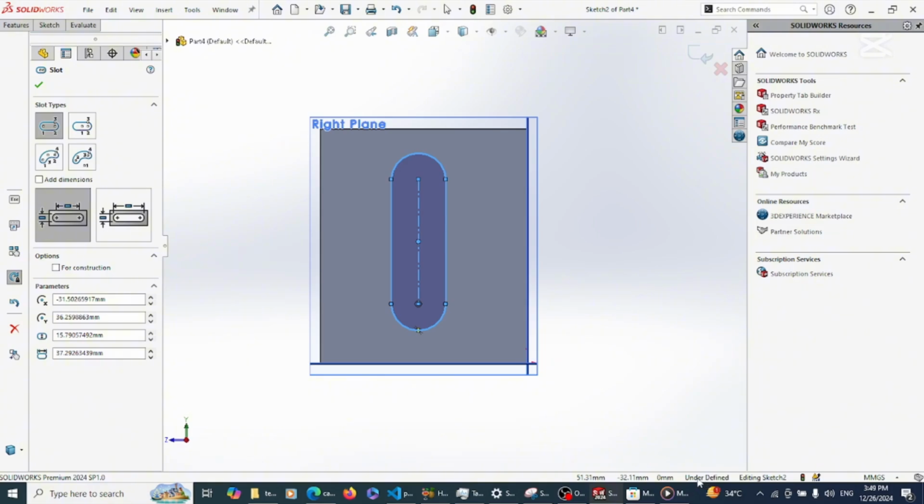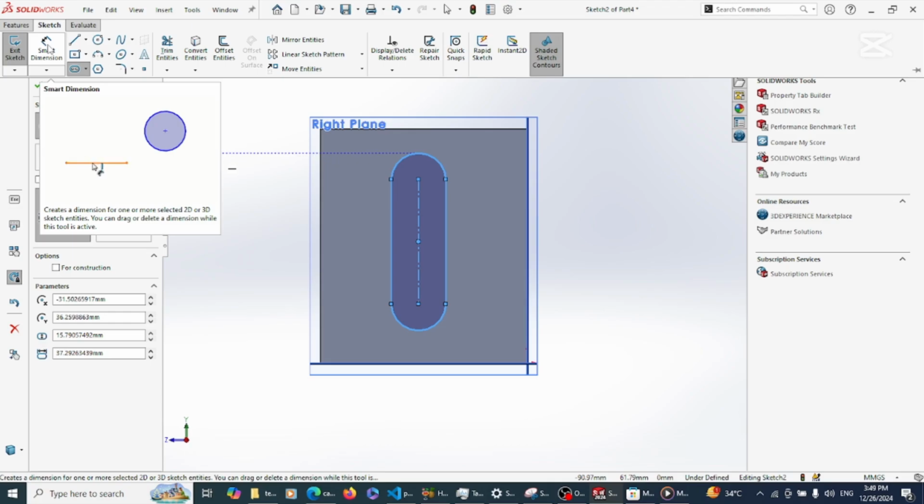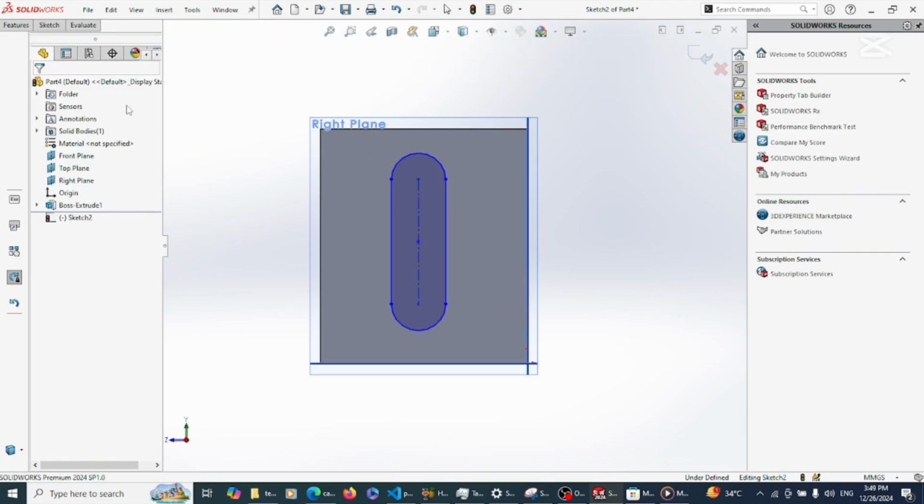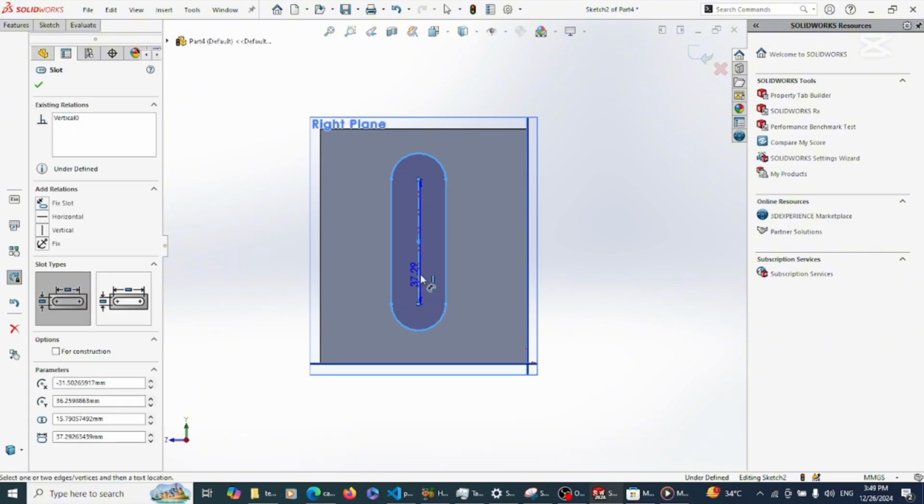Hope you know that it's a good practice to make your sketch fully defined. So actually you are going to define this by giving it dimensions. I can use escape to drop this line tool, but since I want to pick another tool, it's not compulsory to drop the tool. I'll just go to smart dimension to drop the line tool and pick the smart dimension tool. So to dimension this, I can either choose this point and this point, or just choose this line, give it a length. Let's say we give this one 25.